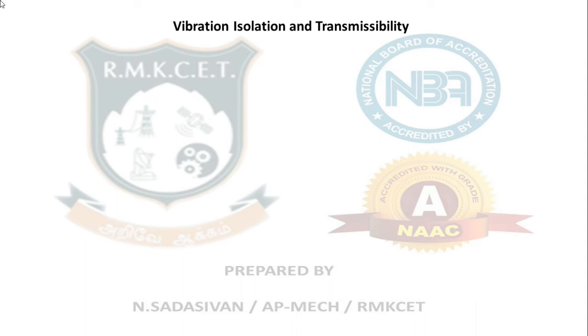If you go back to your manufacturing technology 2, first unit, mechanics of metal cutting, you would have come across a merchant's circle diagram where you have studied about three different forces encountered by a single point cutting tool. What are they? The cutting force, thrust force, and the feed force. Three different mutually perpendicular forces react on the job from the tool, and you get reaction forces on the tool.